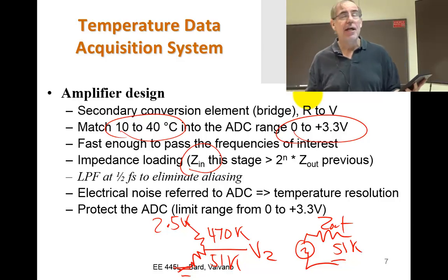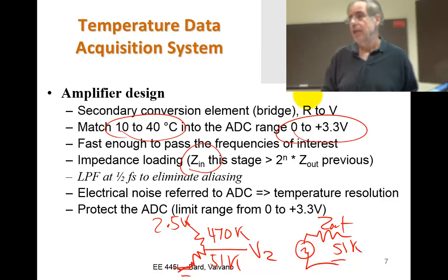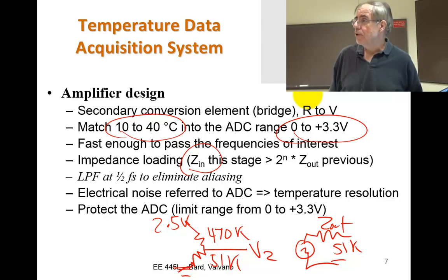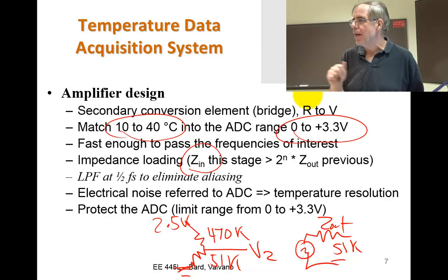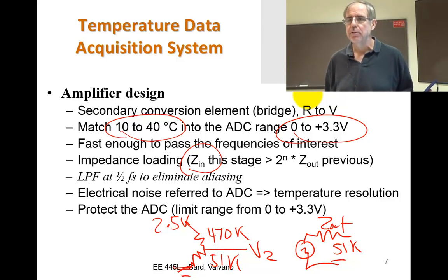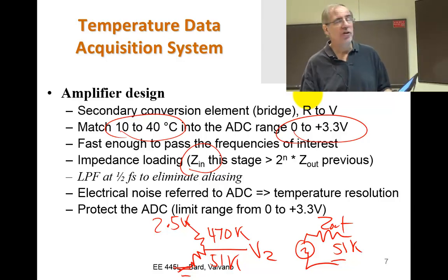The amplifiers have a wonderful thing. They can also be the frontline for spurious inputs. Somebody plugs 120 volts AC into that connector because they're bent on doing something stupid. It'll burn out this instrumentation amp, but probably will not burn out your processor. So these chips have a bit of a fuse to them.